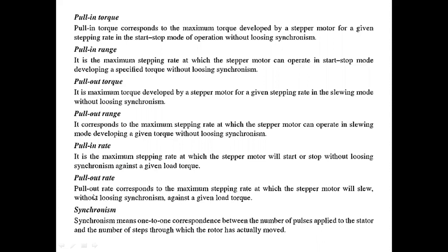Next one, pull-out rate. Pull-out rate corresponds to the maximum stepping rate at which the stepper motor will slew without losing synchronism. Pull-in and pull-out come under these two modes of operation, so start-stop and also slewing.